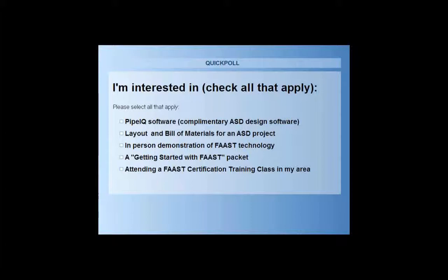Total amount allowed for the system is 328 feet of pipe. So that's when you start adding T's and bends and so forth. When you start adding a lot of those, the software, again, is very user-friendly when you design a system. It does not allow you to go outside of the operating specs of the product, so it's not like you can mistakenly design a system that is not going to be compliant or that won't work. So that's all fully supervised.